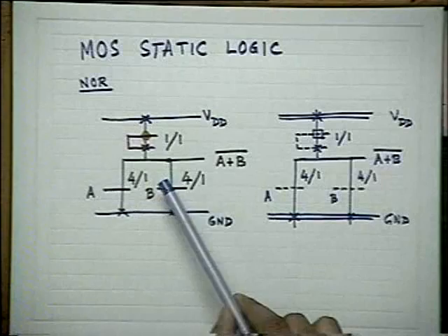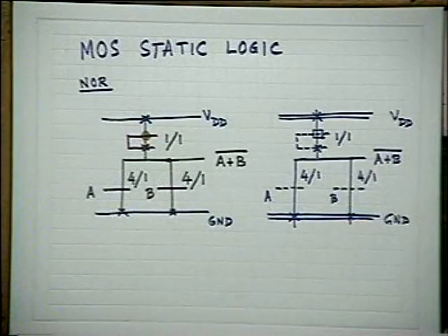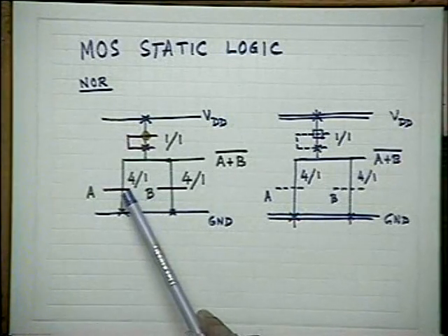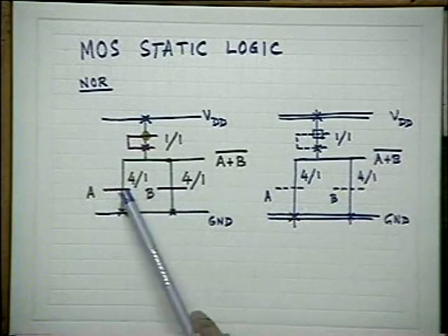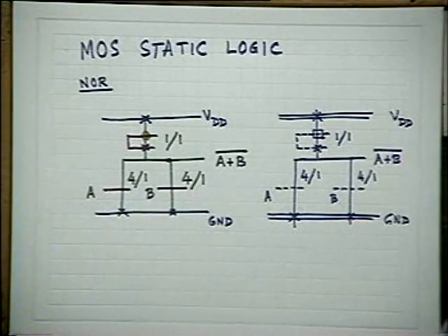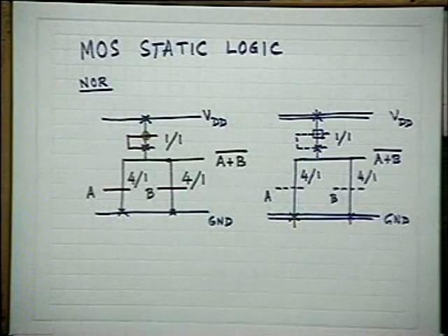We don't require a high beta R. Typically around 4, 5, I said; the example is full. 4 and 5 normally does serve the purpose. But if it was a saturated load, naturally this same thing would have been some 50/1. Please remember this. Now I have assumed the same W/L ratio for both driver transistors, and that is 4, the optimum value. Is it logical?